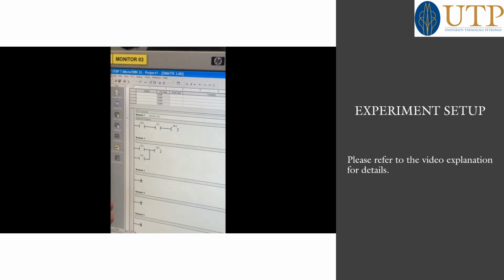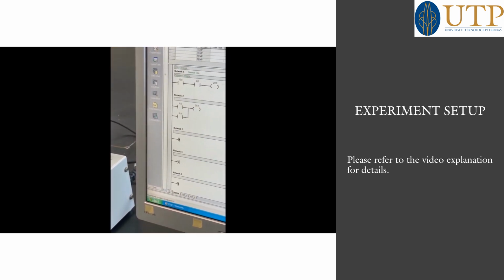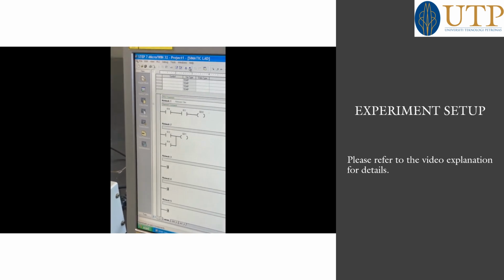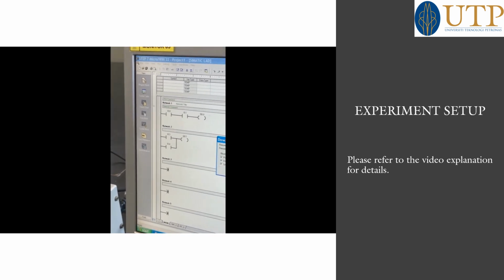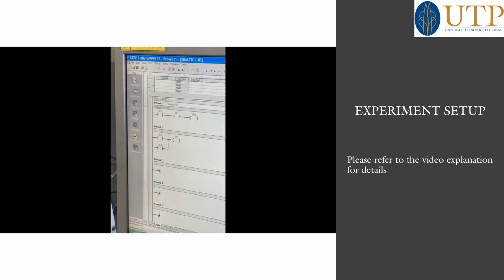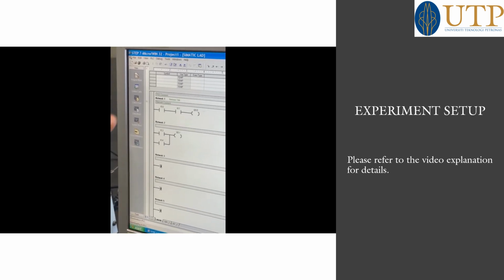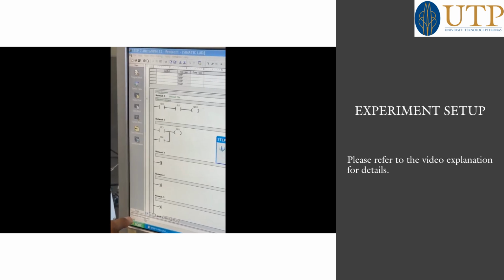Now you need to download the code to the transmission box, that is the PLC box. So click on this down arrow. So it will ask to download which blocks, that is program block, data block, system block. Select everything, click OK. So if you find any errors, it will show here the errors, some errors regarding network 1, network 2. So this is called network 1, this is network 2. So it will show where is the error. So now if the code is okay, it will show that download was successful.